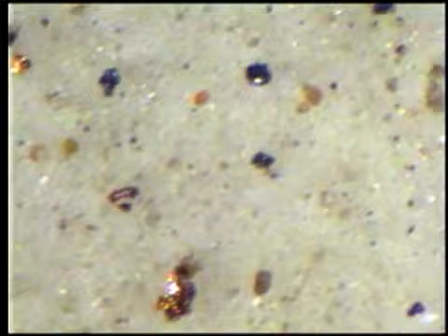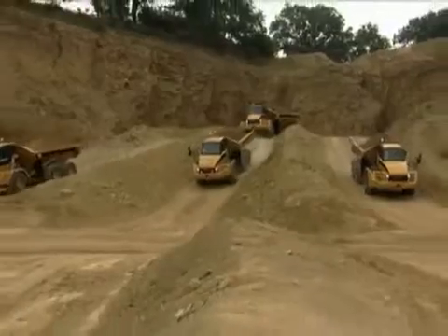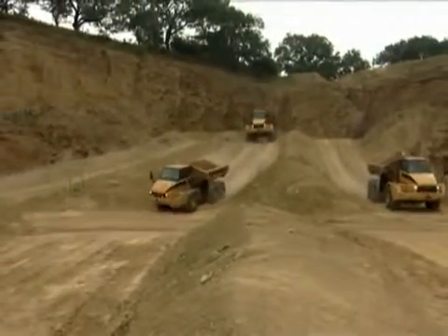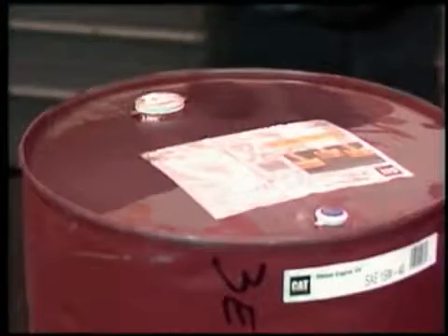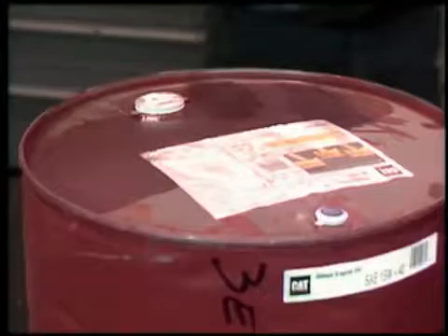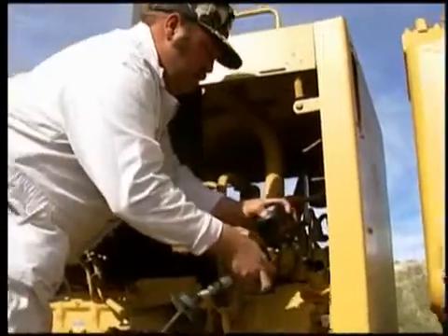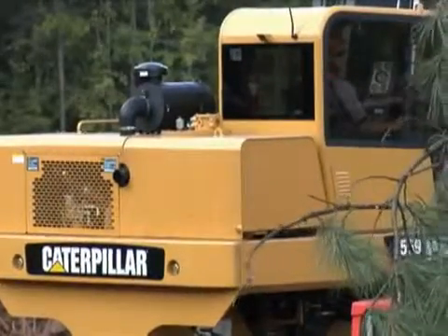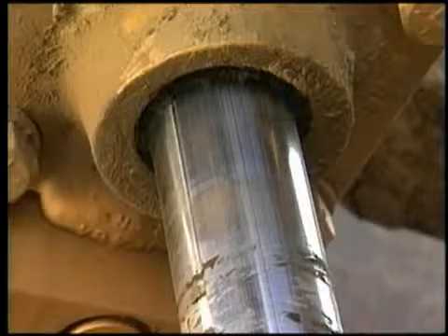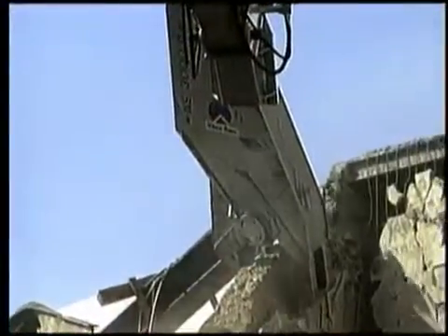These particles look like this in dirty oil. A microscope reveals the actual difference in appearance between dirty oil and clean oil. Small particles can take advantage of a lot of opportunities to enter a closed fluid system. They can get in when the component or machine is built, during the storage or transportation of new oil, during maintenance and service when the system is open for repairs or oil changes, and during machine operation, such as around worn wiper seals or when attachments with dirty connectors or dirty oil are changed.